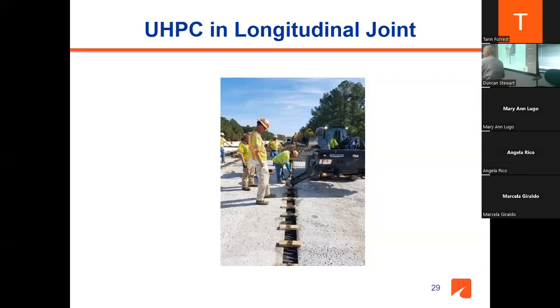I'm sorry for the interruption, but what we are talking about is that when we are connecting and there are reinforcements coming from both sides of this structure, it is very important that you have very short splices.